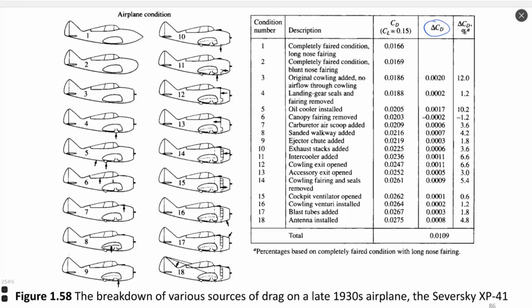Of course, the engine will not change. The engine will be the same. But what happens when drag coefficient changes is that maximum velocity changes, and the stall velocity of this airplane changes. Okay, when drag changes, it changes the flight velocity, and there can be a significant difference.